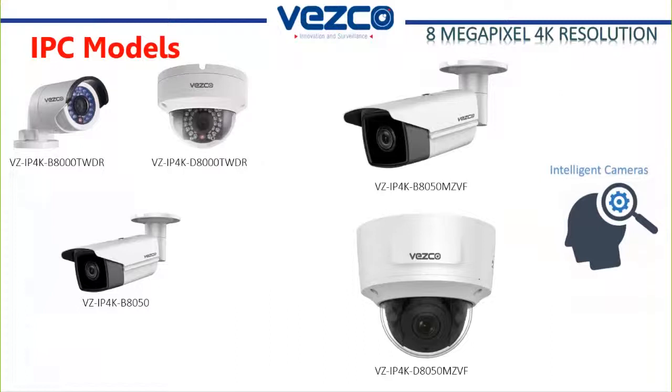Then we have a standard fixed lens bullet. This has digital WDR of 120 dB. So it should be considered true WDR already, but since we have one that's even better, we named it down. If you were to compare the bottom camera here, the 8050, to most true WDRs, it will completely fit inside that category. It's a standard fixed lens. All of our fixed lenses are 2.8 millimeters. All of our varifocals are 2.8 to 12 millimeters.